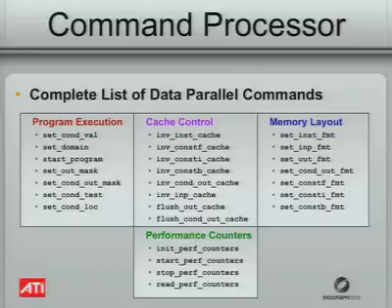You also have controls for validating and invalidating your cache. So the application explicitly controls cache invalidation. In this sense, this includes instructions and constants, as well as inputs and outputs. And the conditionals, which are the conditional commands, are again tied to the early Z testing. We also provide explicit control over the memory layout in terms of the formats and locations. The application actually specifies where all the memory resources are located and their formats.